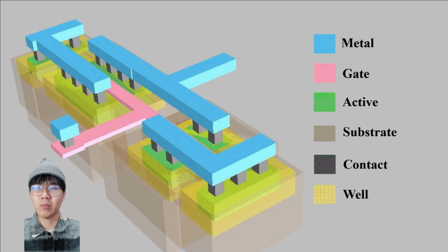These metal layers are responsible for routing signals, connecting the source and drain region of transistor to other components, and facilitate the communication between different parts of the integrated circuit. Second, pink color represents the gate mask. It consists of gate terminals, polysilicon, as well as a layer of gate oxide. The gate structure of NMOS and PMOS are typically aligned in a way that they occupy the same physical space.